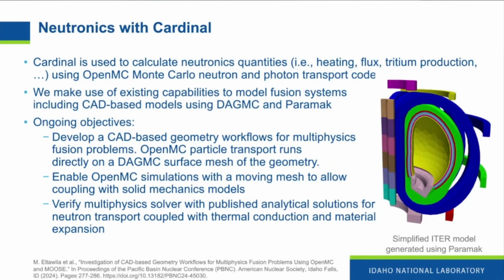I'll go over this very quickly, but this is highlighting some of the results that we've obtained, coupling OpenMC with Moose and trying to streamline that workflow. We saw that one of the main barriers to engineering studies was creating the mesh and then making sure that we use the mesh for OpenMC or neutronics calculation, and then can transfer the information easily between OpenMC and the other physics within Moose. And so what Mahmoud and April here at UIUC have done is that they demonstrated a CAD-based workflow using those tools.